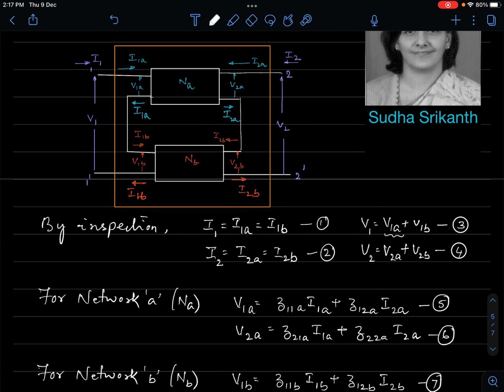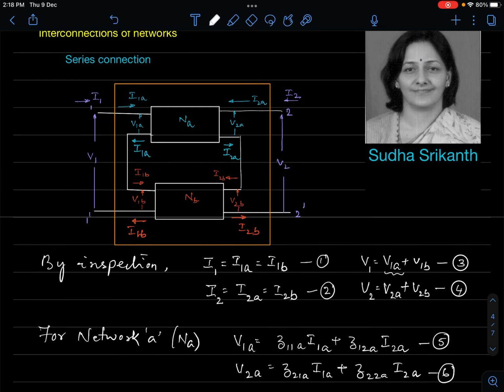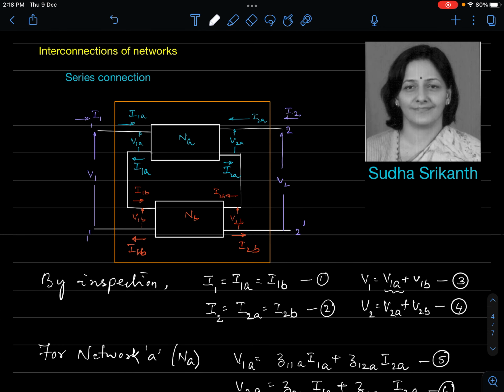So whenever you have two networks in series, get the Z parameters of the resultant network, and if you are interested in, let us say, ABCD parameters, you can always obtain them from Z parameters. We can do that derivation from one parameter to another. It is very simple fundamentals. If you do it for one, you can extend the concept to any other. Y parameters can be expressed in Z parameters and vice versa. We have six sets of parameters, and all six can be interchangeably expressed in terms of one another.